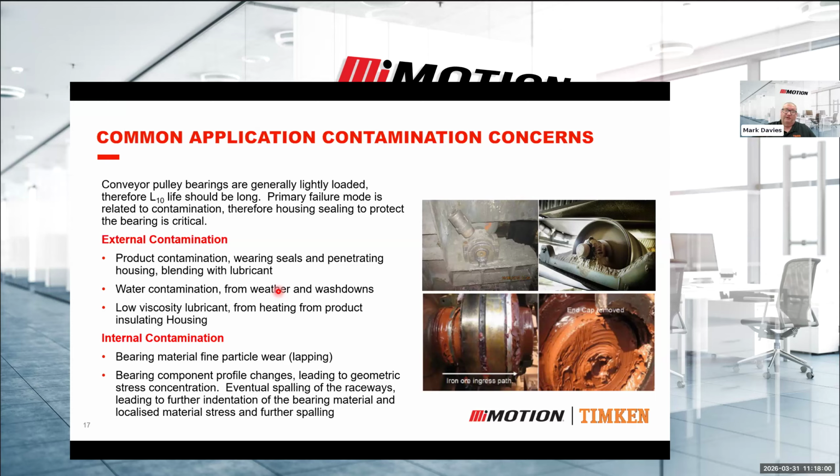From a theoretical point of view, the L10 or the theoretical life of the spherical roller bearing on inside these housed units should be very long, because the sphericals are loaded very lightly. The design of the conveyor is based on the shaft deflection, how much load, how long it is, how much deflection the shaft will give, and usually that means the shaft diameter is quite large, and then they select the bearing size for that shaft diameter.